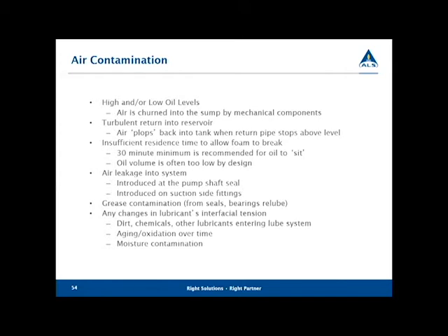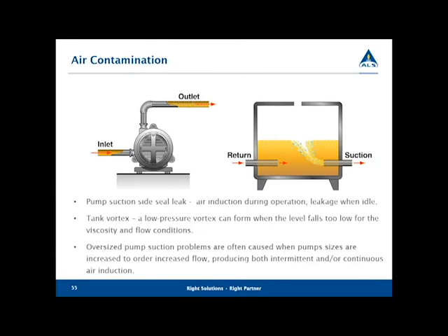A lot of times if you reassemble equipment, the mechanic will actually use grease to fit the parts together. Well, if that's not cleaned out properly, that can bring in some foaming. And any change in lubricant's interfacial tension, dirt, chemicals, aging, moisture contamination, all lead to foaming and aeration. There's just a little schematic of what happens on the return line from the suction line.